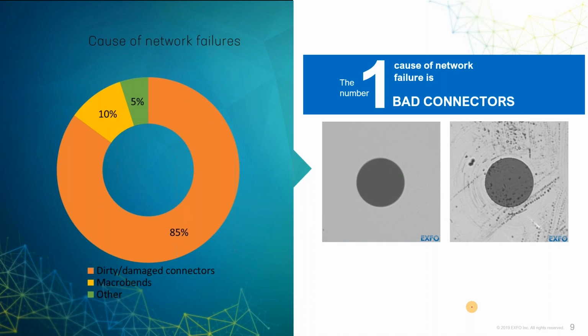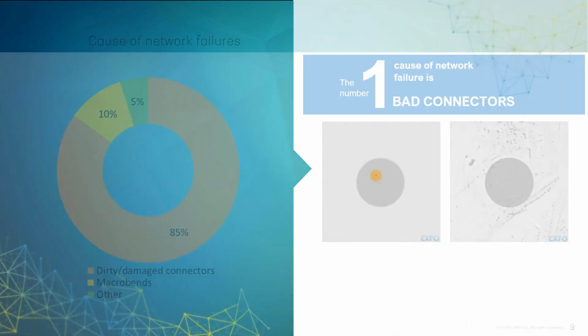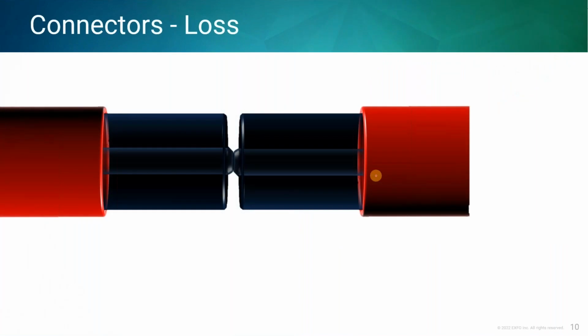And by the time someone like me looks at it and says, "Oh man, it's that panel's dirty," or "There's something wrong there," we don't know, so it has to be retested, which means an additional truck roll. And to a very large degree, these are connectors. So when I talk about testing, I'm going to focus on validating your trace before you move on to the next fiber, because that's part of reducing the truck roll stuff, right?